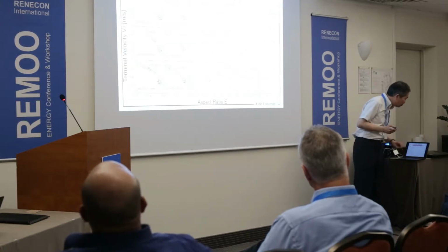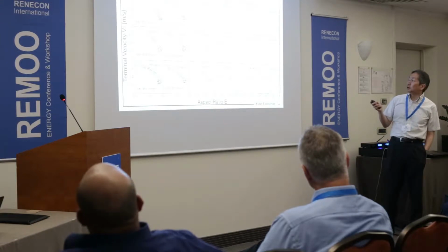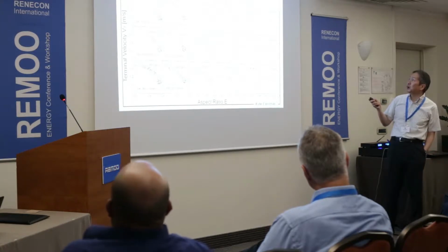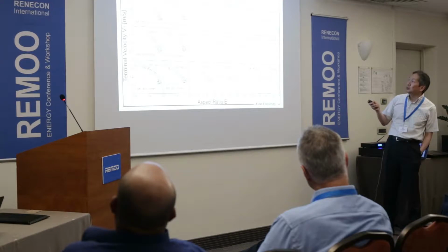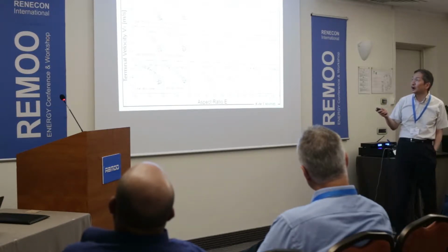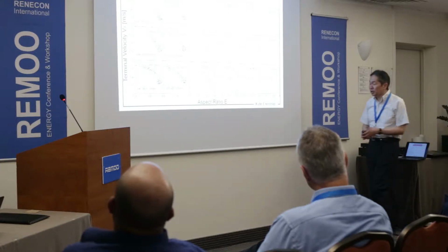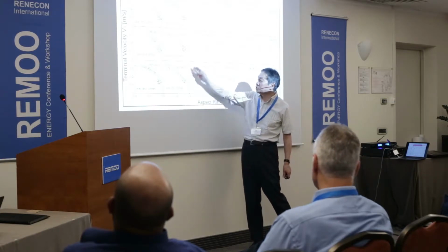In the simplest case, you can get this expression for the terminal rising velocity. It's a function of the bubble aspect ratio and fluid properties. And from this you can get this expression for the drag coefficient, which is a function of the Eötvös number and bubble shape. And here I plotted the aspect ratio against the terminal rising velocity.